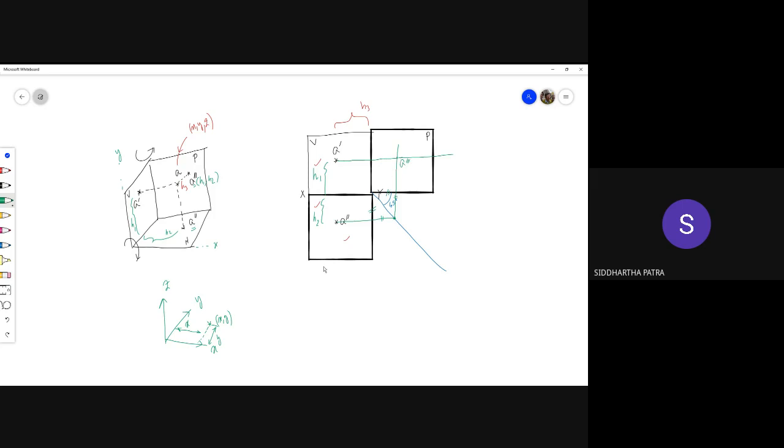The other way to do that would be to let this horizontal line intersect with the border of your horizontal plane, and taking the intersection of the three planes as a center, you can call this point O. So take O as a center and draw a quarter circle, which would ensure that this length is the same as this length.